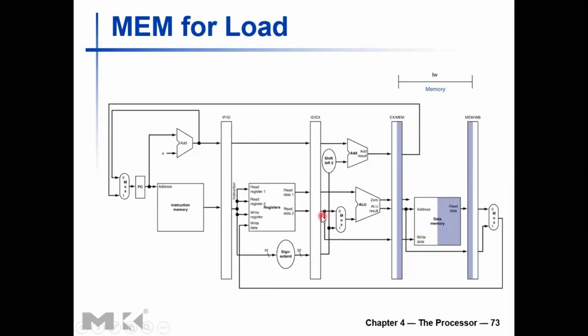But note that the second register value, which was anyway read from the register file, regardless of whether this is a load or store instruction, will have propagated through the IDEX pipeline register, being discarded here, but propagated through that line into the EXMEM pipeline register and then sent to this write data port of the memory.